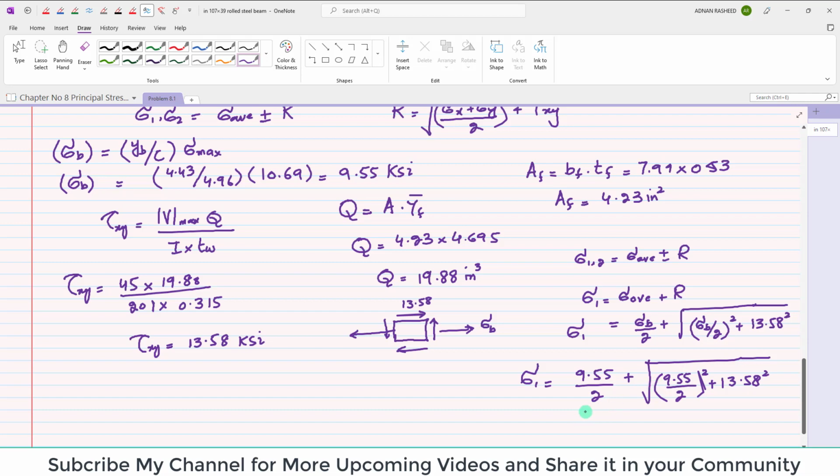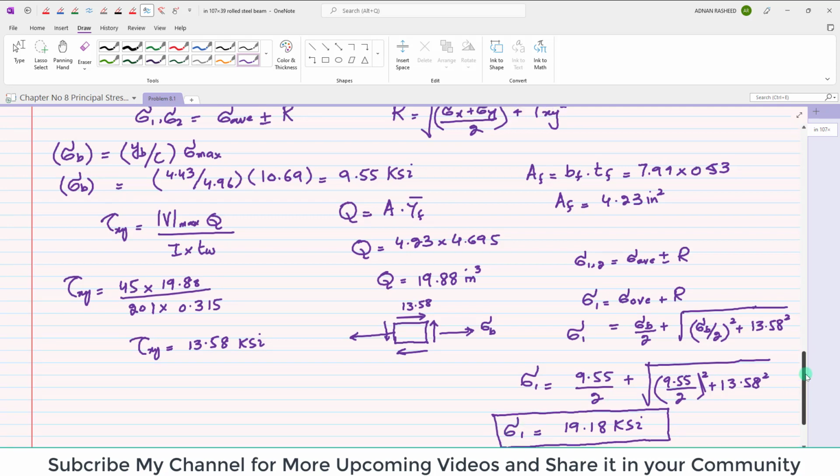When you calculate it, this sigma 1 is equal to 19.18 KSI. So this is the principal stress at the junction of flange and web.